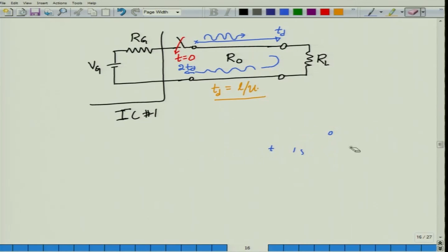How do we analyze, how do we understand the propagation of the step voltage here? There are various methods that have been followed to understand this voltage propagation in the transient or the time domain behavior. What I would like to just remind you is one simple fact. We started off when discussing the transmission line theory or the solutions, we said that any voltage of the form f of t minus z by u should be the solution of the voltage equations.